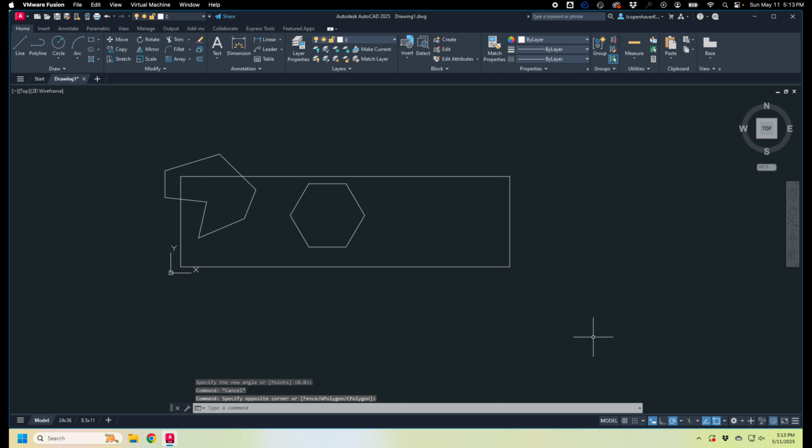It doesn't really matter which one. In general, it's based on whatever you're doing in this particular show. So let's try that without polar tracking. I'm going to Control Z my way out of this. Turn off my polar tracking again. So if I do that without polar tracking, I start my reference there and then there. When I try to go to 0, I got nothing, which means that I can't actually snap to it, which means that I just have to kind of eyeball, and that just sounds like a terrible idea.